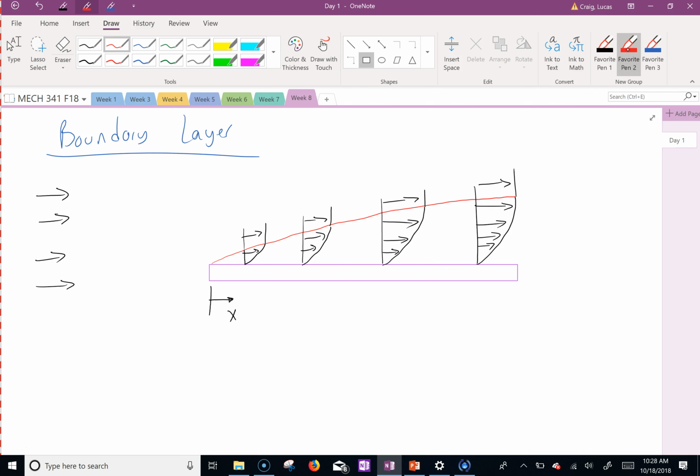Remember when I was talking about my project that I did for my PhD? I had those inlets on the belly of the plane. I had to make sure that, and you don't have to draw this, my shape was outside of the boundary layer to capture free stream air. Because if it was in here, it would be a mixture of whatever's in here, and that's not good. You don't want to do that. So the boundary layer grows as the surface gets longer.